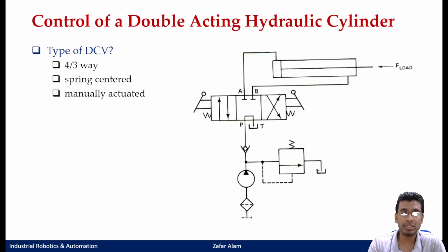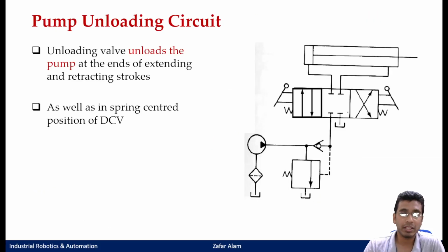So in this case, we have actually put this pressure line, which results in opening of this relief valve, or the construction similar to that of the relief valve, and I am putting it above my check valve here. So what does this do? This will unload the pump.